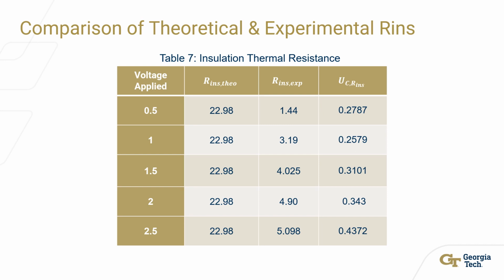There's assumed to be no gradient of temperature, and throughout the experiment, average values were taken at steady state, which does not account for outliers. Furthermore, the system assumes a point source of temperature, which is not true because the system components are not point masses. Adding to this fact that the measurement is on top of the source, there's bound to be error.